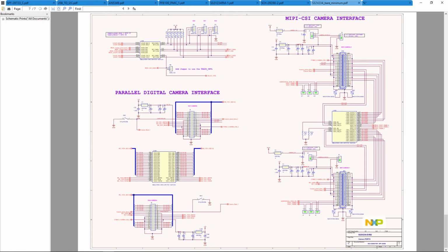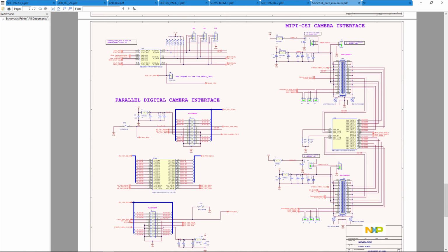And then when we're using MIPI CSI for the camera interface, you would want to have the I2C data, because that's how you communicate and control certain features of the camera. So that's why we have this particular part of the schematic. Yeah, that's what we've done.